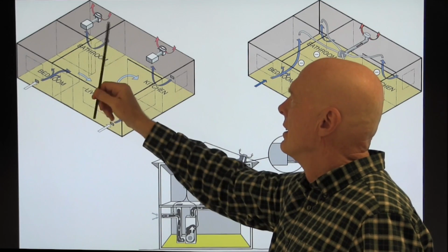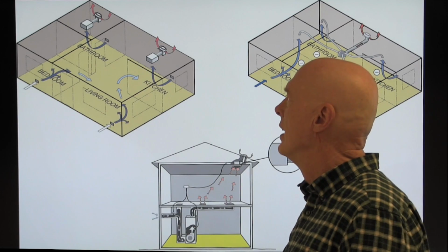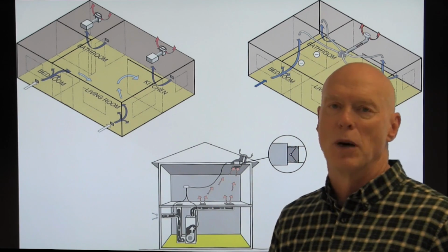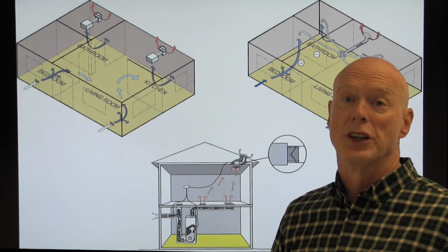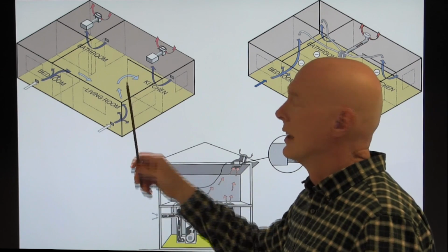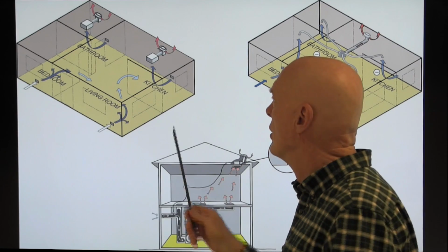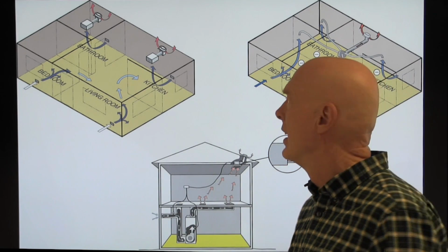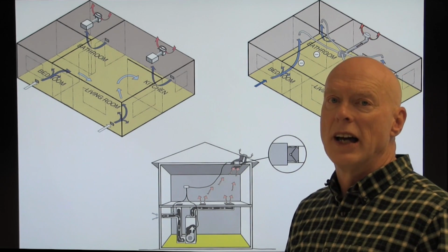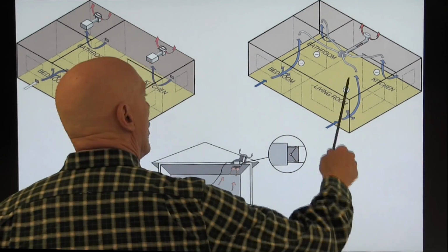We've got a bathroom fan, kitchen fan, we've got windows, and we've got ourselves a home that is maybe somewhere more than 4 air changes an hour at 50 pascals. And so we need a little extra ventilation, and we're using exhaust only ventilation here. We're using existing exhaust fans, just running them longer than we would normally run them, and keeping the air dry and fresh that way.